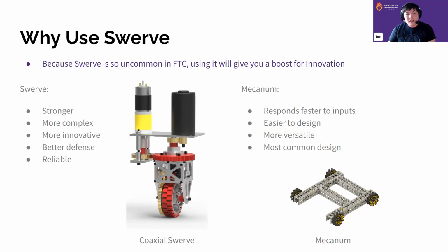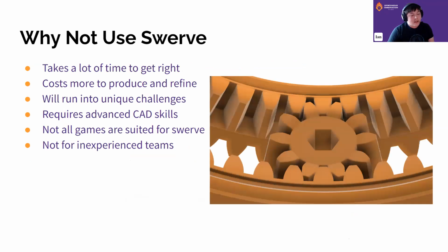While Swerve does have a lot of good things, there are also a couple reasons not to use it. First one is that it takes a lot of time to get right. A lot of teams have to use the entirety of the off-season to properly design and refine their Swerve drive to get it to a competitive level.